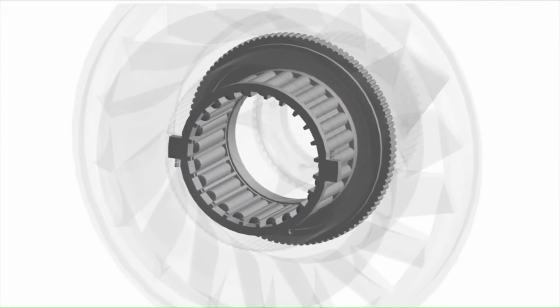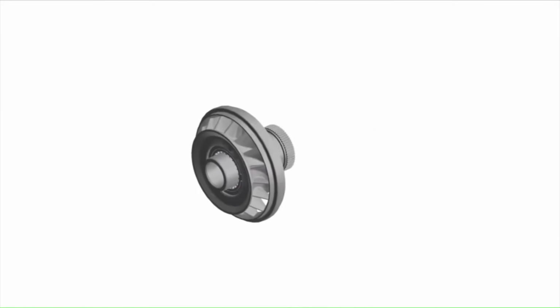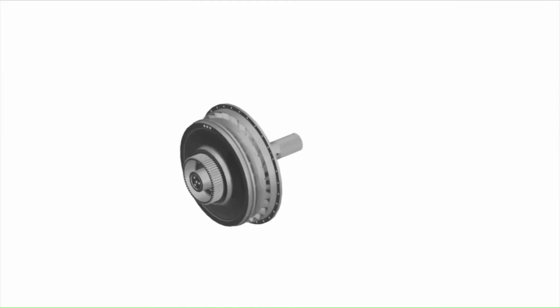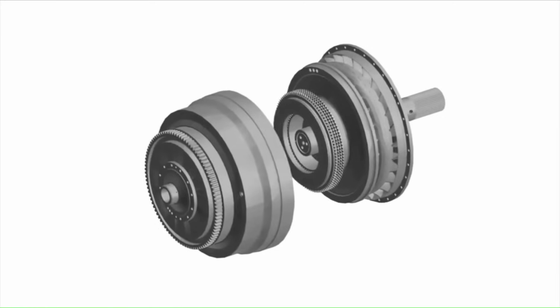In summary, the clutch system and torque converter system serve as the connection between the engine and the transmission, but they operate differently depending on whether the vehicle has a manual or automatic transmission. The clutch is manually operated by the driver to engage and disengage the engine from the transmission in manual transmission vehicles, while the torque converter provides automatic and continuously variable power transfer in automatic transmission vehicles.